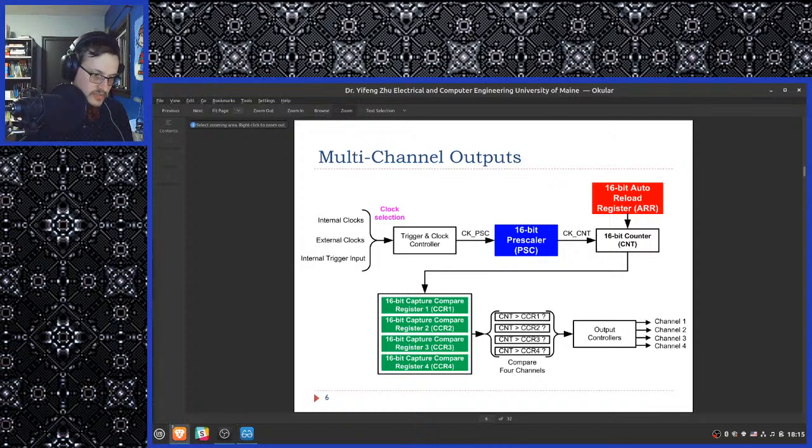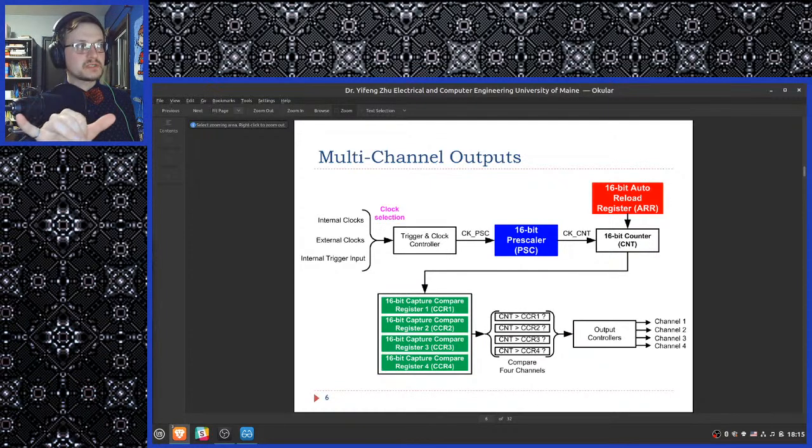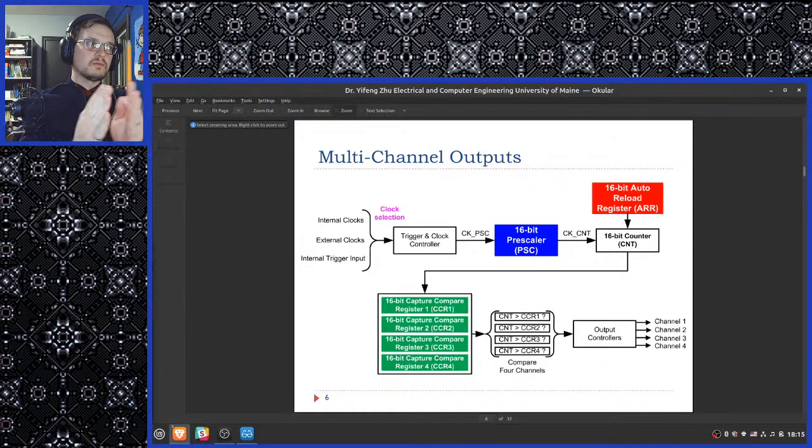The Prescaler is just for different timers on the same board. Well, it can be used for that. So we can adjust the Prescaler for higher or lower frequency. So technically, if we wanted, we could send through the entire frequency of the clock and it just gives us a choice to scale it. Yes. Obviously the Prescaler can't increase the frequency of the clock, but it can slow it down, right? The clock is the maximum frequency available, and the Prescaler draws it out to whatever fits your application.